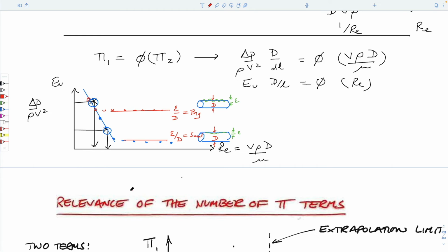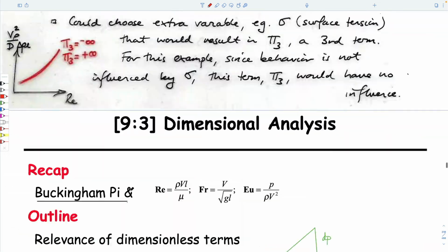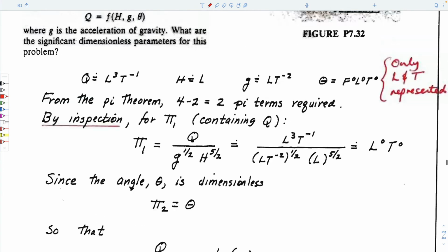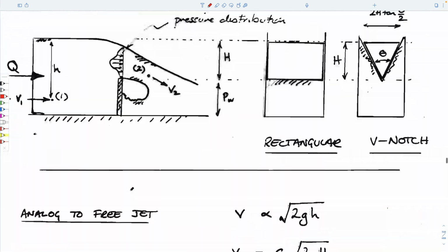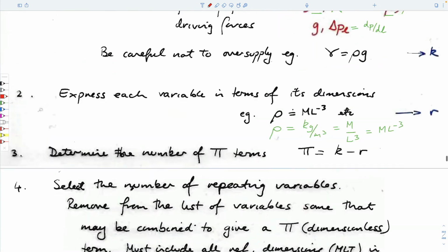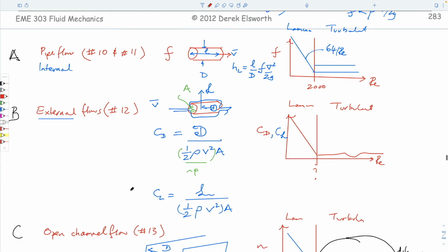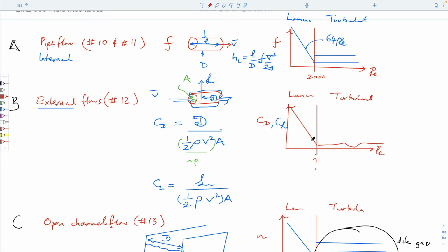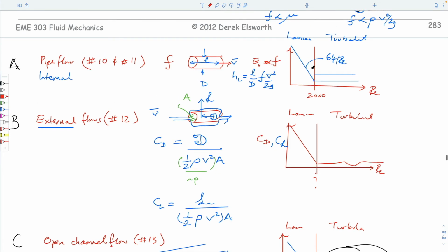And so, if you remember, and I whisk us back to what we talked about last time, we drew all these figures, and we can return to that. These figures that we have here is exactly this. This friction factor is a surrogate for what we've called, it's not the same, it's proportional to, I guess, friction Euler number. And it's exactly this behavior. So in the laminar regime, the flow within a pipe, it doesn't care about the roughness at all. It's completely independent of roughness.